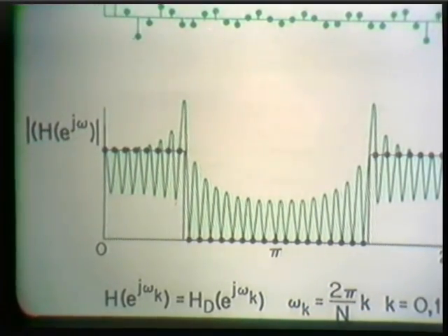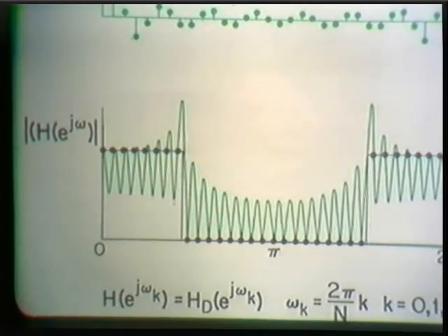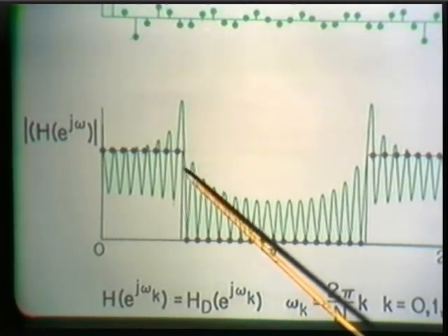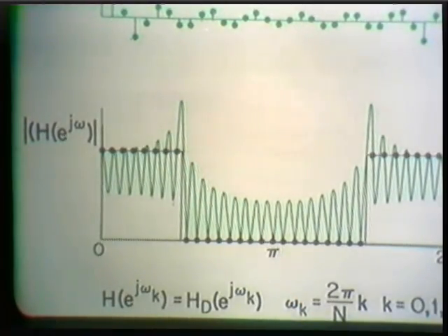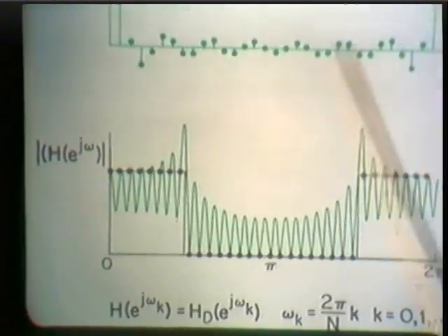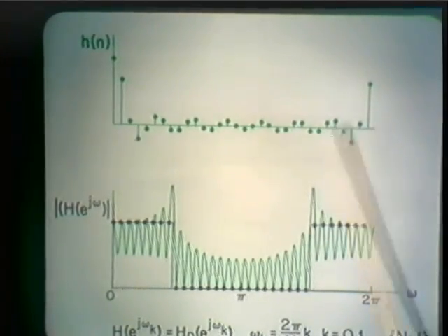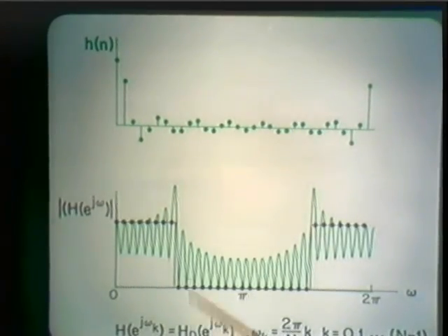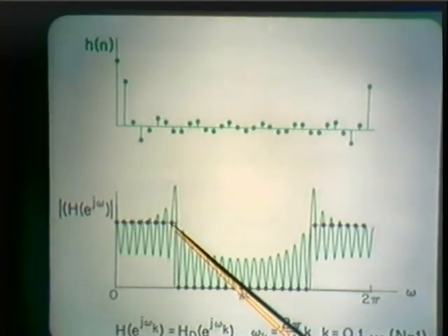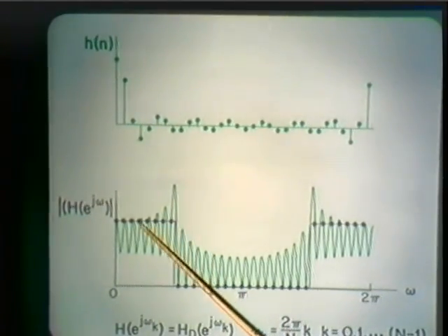All right, so the frequency sampling method is basically a method that consists of specifying samples of the frequency response and then accepting the interpolation in between those samples that is dictated by the form of the unit sample response. And I stress that one has to be careful in the phase that's applied to this, or equivalently the circular shift that's applied to the unit sample response, since, as we've seen in the last several view graphs, that very seriously affects the interpolation in between these frequency points.